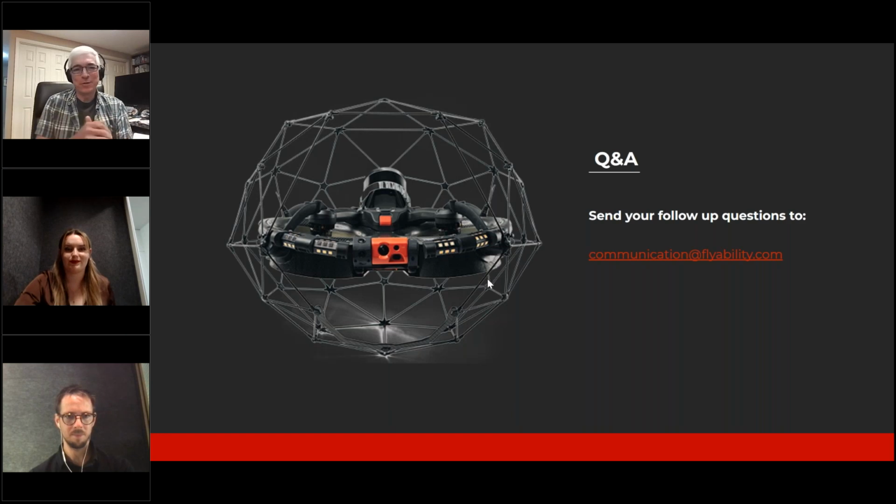Very quickly, I'll answer both of those because we considered both of those. The first one about the dust and being able to image, Flyability engineers already took care of that one with some amazing oblique lighting capability on the drone, so that the lighting is not reflecting right back into the lens of the camera off of the dust particles, and it's amazing how that really helps in terms of your image quality. So the lighting on the drone already takes care of that. It's designed to take good imagery in high dust environments.